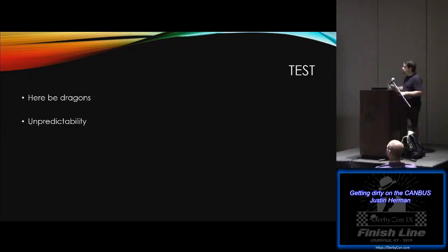When you're testing, obviously there could be dragons there. That's a concern because you're now transmitting onto the bus, and you don't necessarily know what every message that you're sending out does. But hopefully whittling that down using some frequency analysis is a strong way to be able to get yourself in a better position. I did have my car lock up where I needed to power cycle it, but a simple power cycle fixed that.